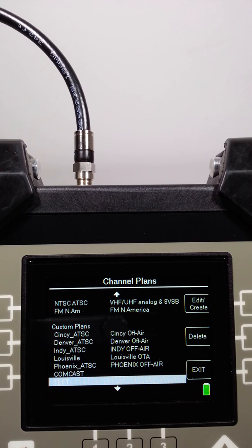The third method that you can use to create a custom channel plan or edit a base plan and create a custom channel plan is on a computer. It's for more advanced users using a text file. If you wish to create a custom channel plan, editing the different fields within a text file, and then transferring that custom channel plan to the XR-3 using the MeterMate application, that's another option.